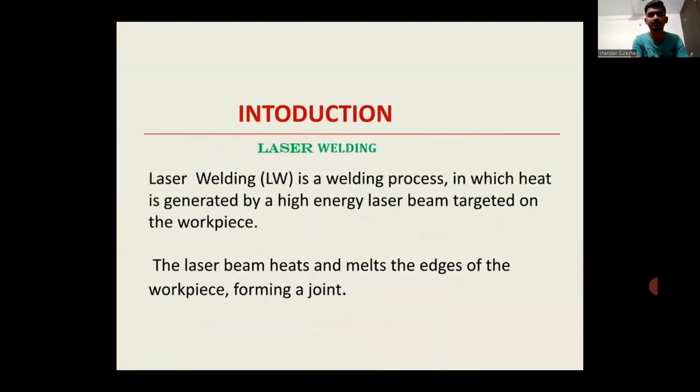Introduction. Laser welding is a welding process in which heat is generated by a high energy laser beam targeted on the workpiece. The laser beam heats and melts the edges of the workpiece, forming a joint.